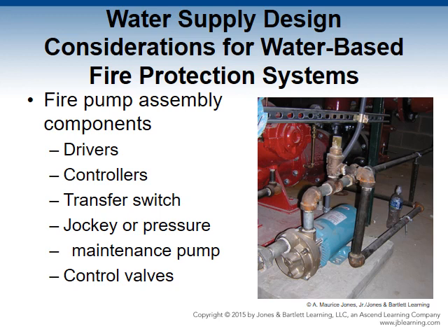A significant amount of water is flowing, so it is important to consider how to manage and dispose of the water. When testing the pump by circulating water through the system, a flow meter measures the fire pump water flow. All flow meters are installed in line with the system piping and measure water as it flows from the discharge side of the pump back to the source.